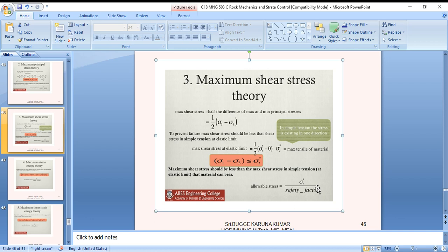The factor of safety can be visualized in such a way. It allows for the difference between the laboratory determination and the in situ strength of the rock, plus the error introduced by the various assumptions required in the computation of stress and deformation. It is necessary to use a safety factor in the treatment of rock structure problems. The safety factor is defined as the ratio of the maximum stress in the material in service, the working load, to the strength of the material.